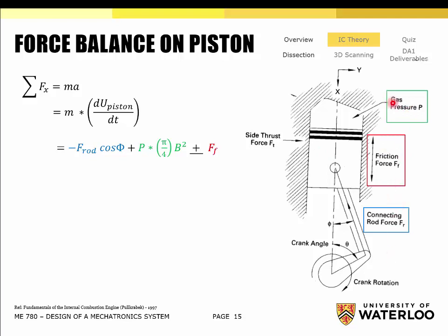Okay. So the gas pressure inside the cylinder. Yes, u is the velocity. So the force inside the cylinder, which is this green area, the force due to the cylinder pressure, which is this green term here, is just the pressure times the area. That's the force here. And is that positive or negative? This is the important part. So if we're in this stroke of the engine where we're producing work, it's positive. By convention, let's say positive is down, okay?